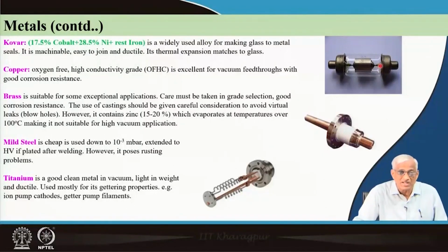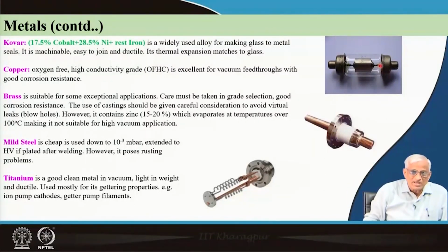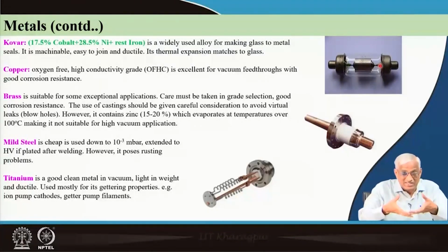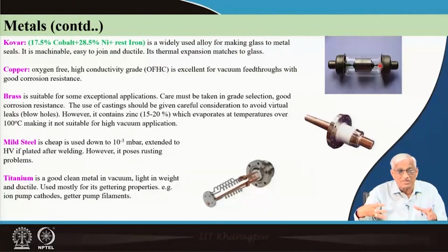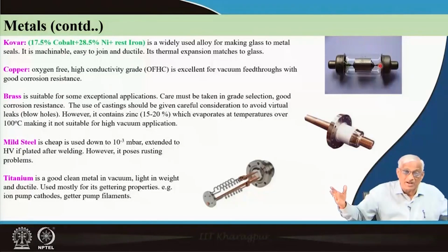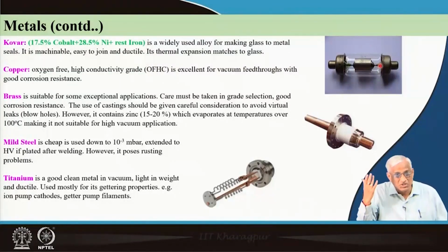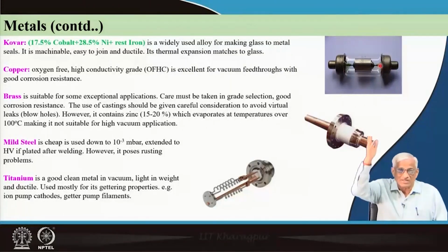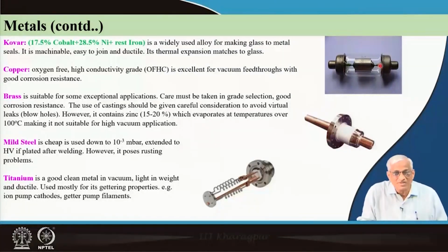A vacuum interrupter sitting in the high power lines has to stand 20 years without losing vacuum at 10 power minus 7 torr. It has a ceramic bonded to metal caps with a huge amount of copper electrodes passing high current and high voltage, 110 kV, 3 kiloamperes, waiting for a fault to come. This is a safety interrupter.